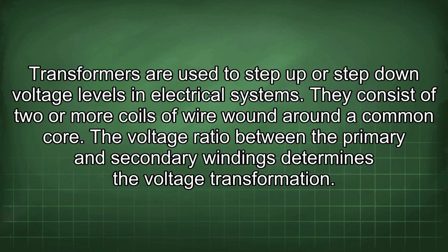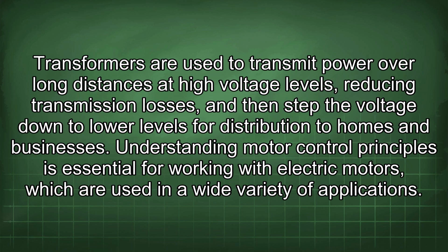Transformers are used to step up or step down voltage levels in electrical systems. They consist of two or more coils of wire wound around a common core. The voltage ratio between the primary and secondary windings determines the voltage transformation. Transformers are used to transmit power over long distances at high voltage levels, reducing transmission losses, and then step the voltage down to lower levels for distribution to homes and businesses.